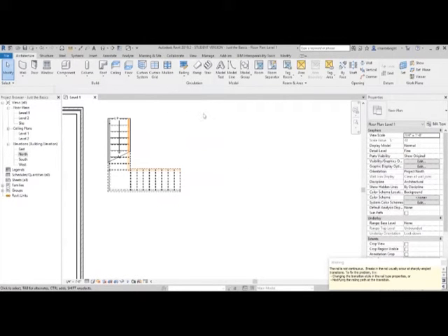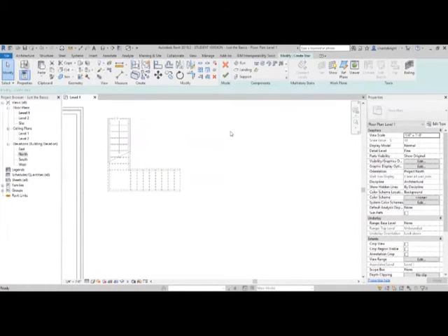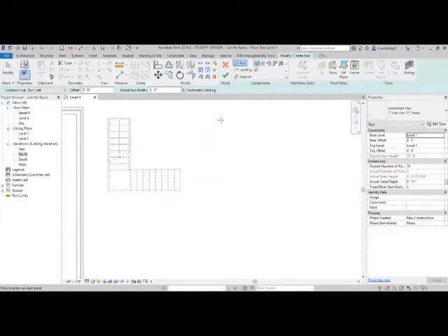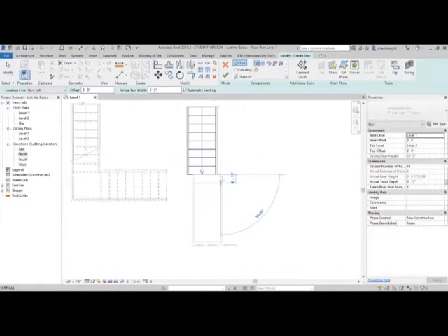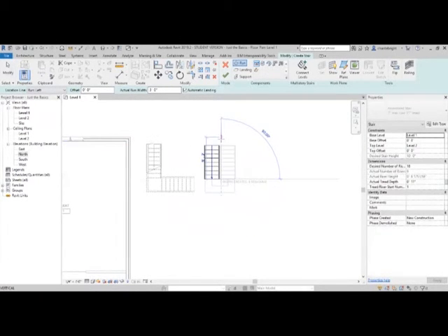You can also do a switchback stair, and like I said, I'm doing this very, very fast, so there's some things that I'm skipping. But if you want to do a switchback stair, once again, you look and see how many it creates. You then go back and switch your run, and I'm going to keep it at run left. I'm going to provide a little bit of space in this one this time. And I take it and I go back, and there's my switchback stair.